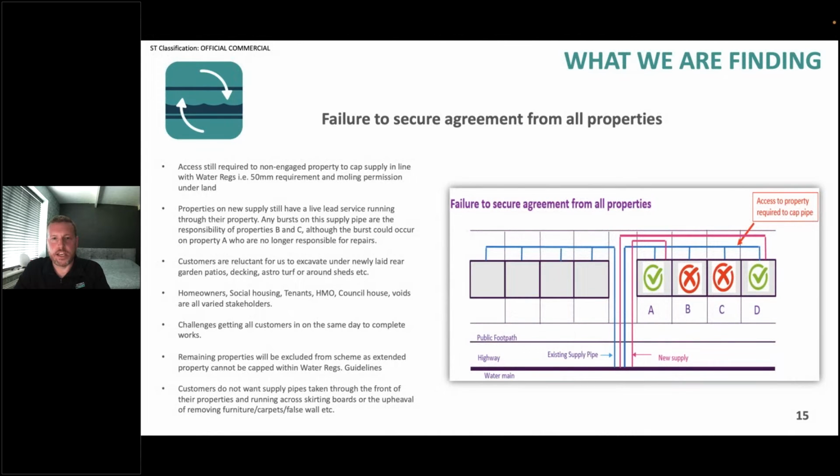They're usually in kitchens, behind cupboards, behind washing machines, dishwashers, and it's quite hard to get onto the stop taps. Usually there's just a hole big enough cut so you can get your hand onto it, and this touches on why we started speaking to Mueller about how we could define what the material types were, because sometimes you could just see the tap and you couldn't even see the pipe material coming up from the floor.